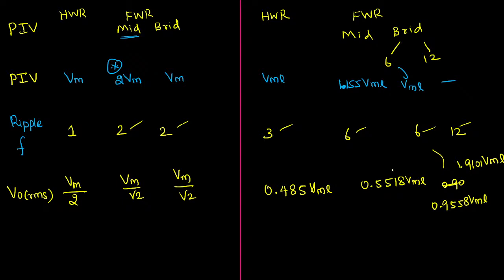Fine. So what I'm requesting you is, apart from that, there are some things that you have to observe, like how to write down the output voltage expression for single phase diode rectifier. If we take only half wave rectifier, connecting only a diode, with input AC supply, single diode, and output, if you connect R load, what can be the output voltage?